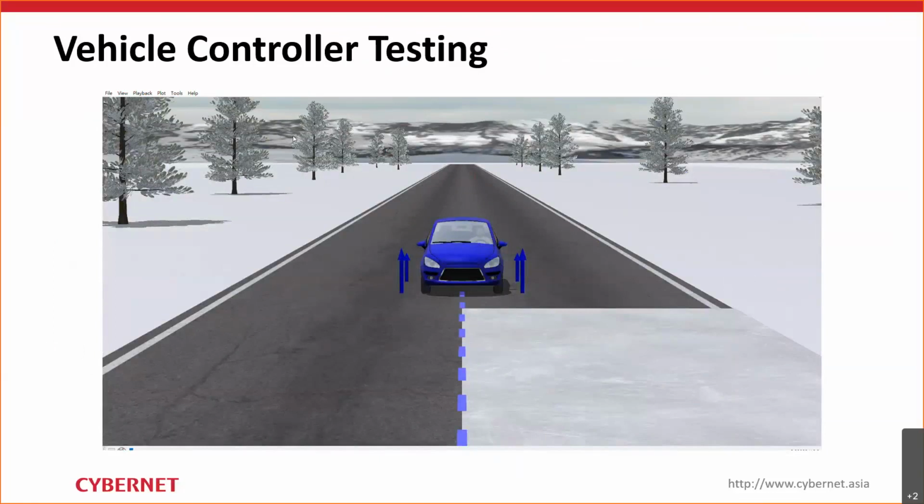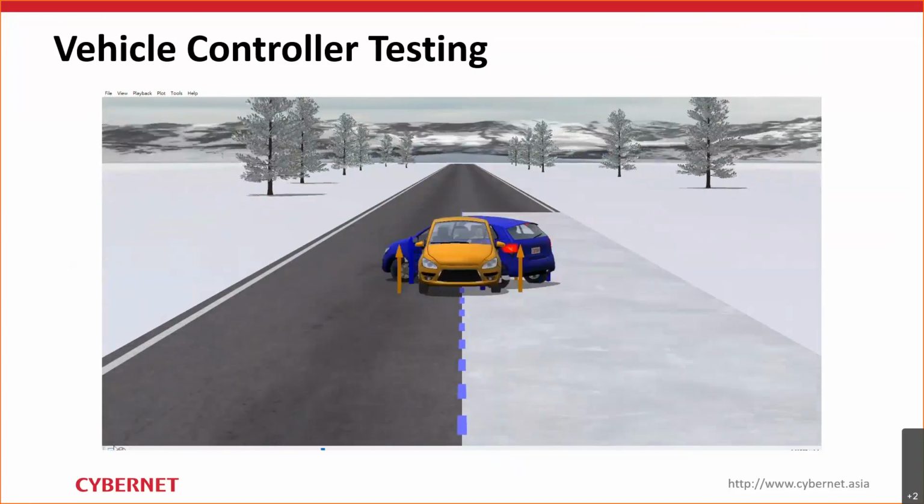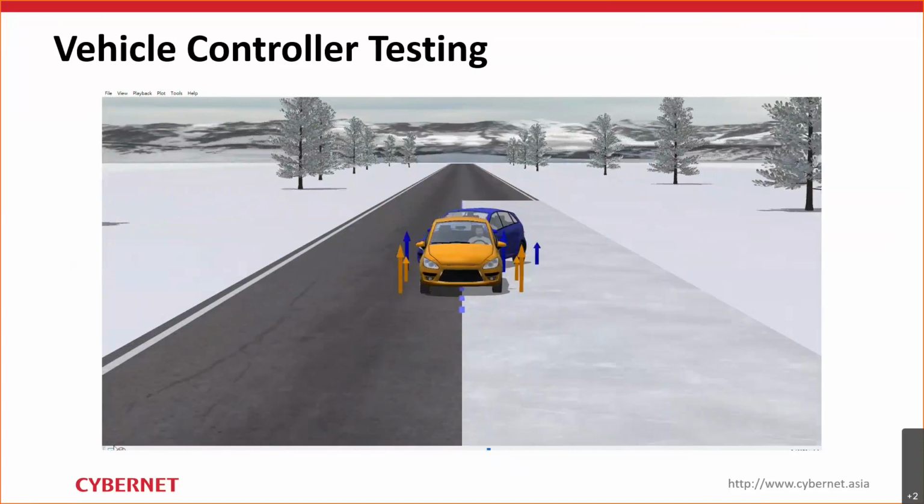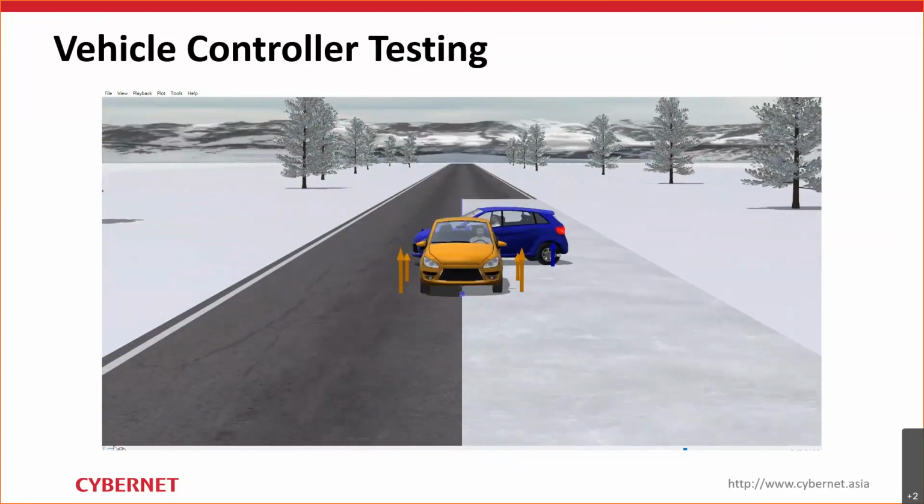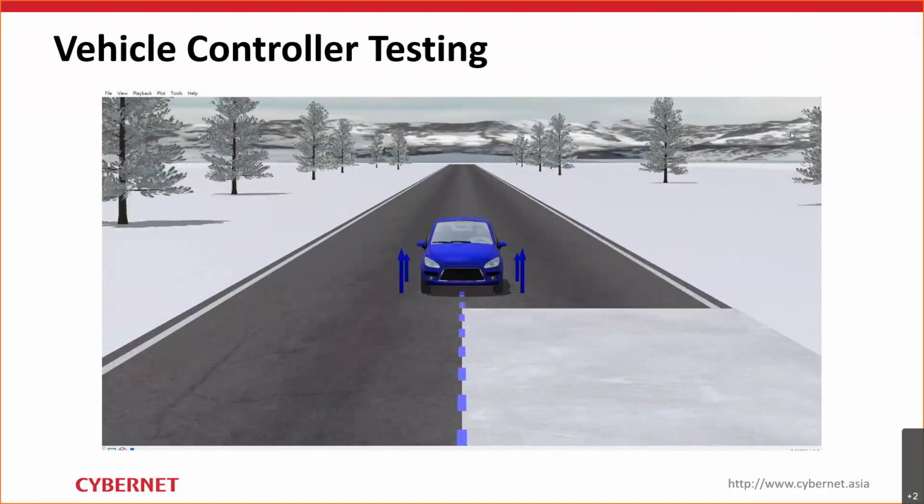So let us take ABS system testing as an example. We can overlap two kinds of simulation results, with or without the ABS controller, on a split friction road. Testing and comparing with different kinds of models will be easier and cheaper. We can use this to develop and tune our controller at very low cost. This is how we build vehicle models and develop controllers with simulation tools, quicker and safer.